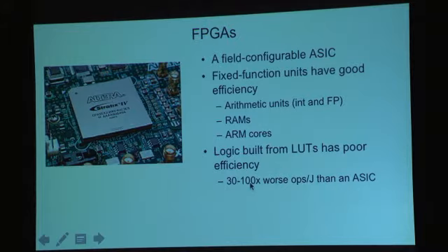We've actually done some prototyping studies, and it wound up sort of with the FPGA typically being about 100x worse than the ASIC for anything that doesn't actually fit into the fixed function units. And so this usually winds up being sort of the demise of FPGAs, particularly if you want to do things like reduced precision. The recent Arria and Stratix parts from Altera, now Intel, for example, have 32-bit floating point units, but they don't have 16-bit floating point units. If you wanted to reduce precision and do 16-bit floating point, you'd be down a factor of 100. You're better off doing the 32-bit floating point.